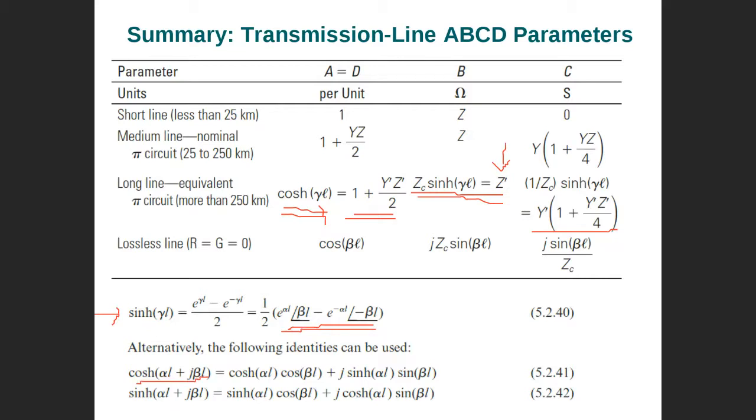You can do the cosine hyperbolic of the real part by calculator, times the cosine of the imaginary part, which is beta. So this is alpha plus j beta. This will be a number and this will be a number, so you just plug in the real part number and the imaginary part number, and the j, you plug in here. So the complex cosine hyperbolic, we plug it here. You better use these.